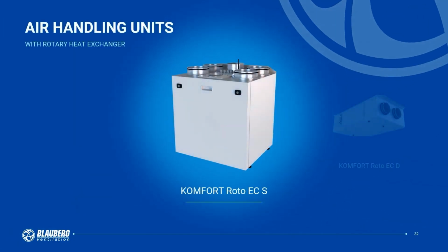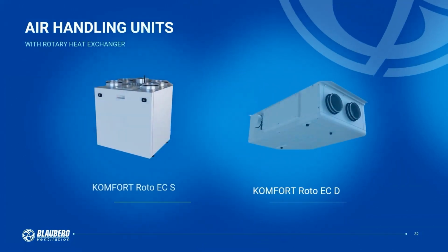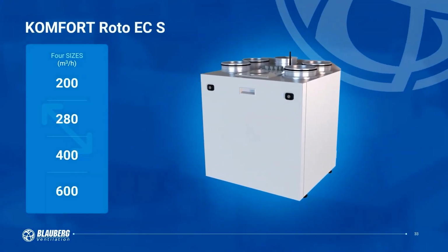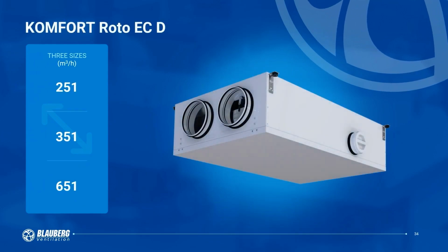Next, let's move on to units with rotary regenerators. Vertical units available in 4 sizes with a maximum airflow rate of up to 600 cubic meters per hour. These units can be additionally equipped with built-in heaters for regions with cold climates. Suspended units available in 3 sizes with a maximum airflow rate of up to 700 cubic meters per hour.